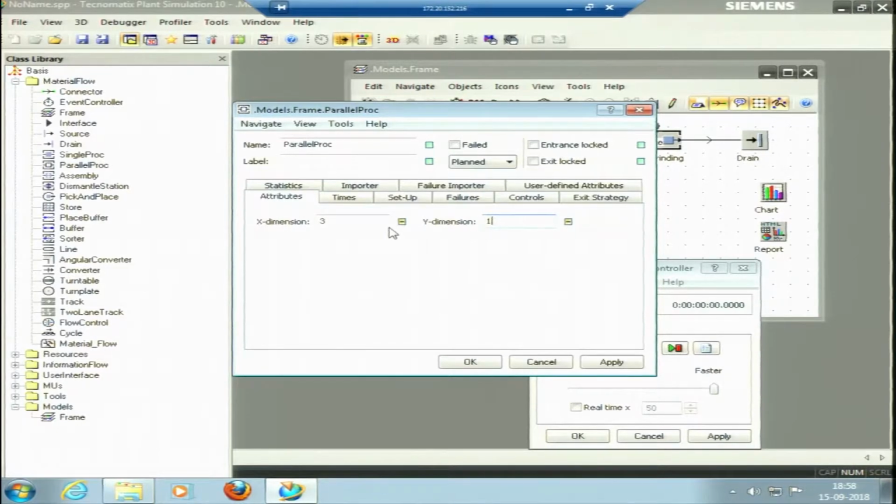In the case of process layout, we have a specific set of machines in one section, another set of machines in another section. If we see the overall machine time, and in this specific section for 30% of the time there is a blockage, or waiting I would say, we can consider that 30% of the time is waiting, and we can give them some other job. Some other job could be given.